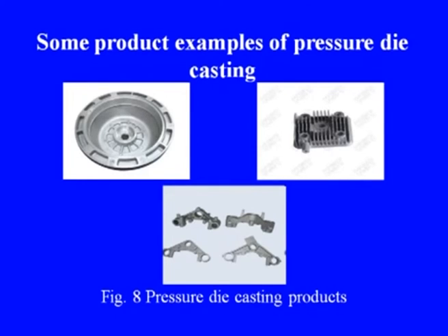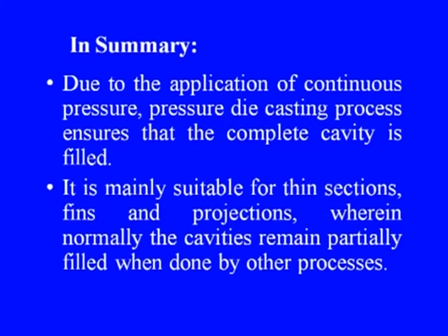In summary, it can be said that due to the application of continuous pressure, the pressure die casting process ensures that the complete cavity is filled. It is mainly suitable for thin sections, fins and projections, wherein normally the cavities remain partially filled when done by other processes.